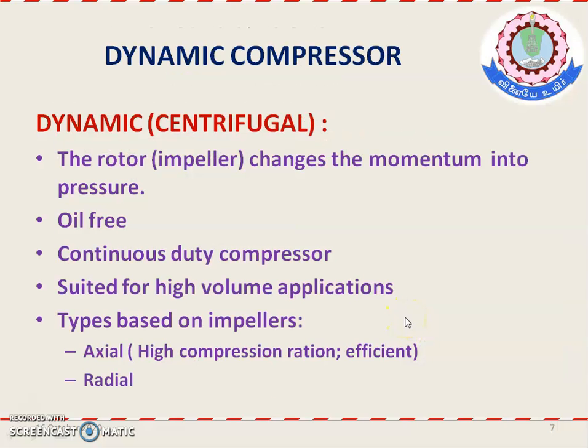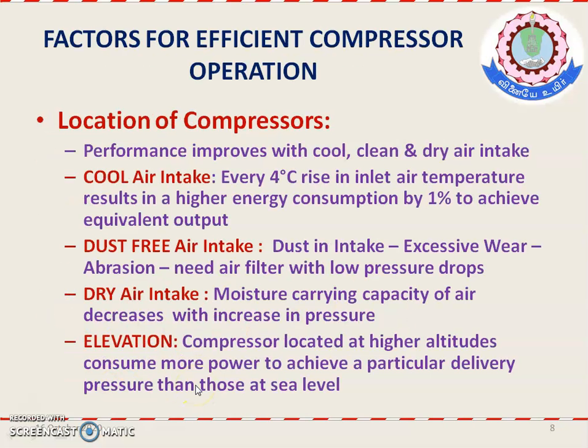And another one is dynamic compressors, where the rotor or impeller changes the momentum into pressure. That means your velocity will be increased, and thereby your pressure increases. Oil free: there is no cooling oil, and thereby there is no mixing of oil with your working fluid. Continuous duty compressor, which can be operated continuously and is suited for high volume applications, and types based on the impellers: axial and radial types.